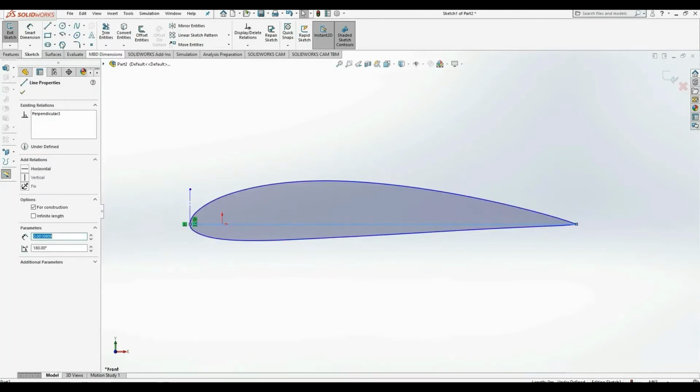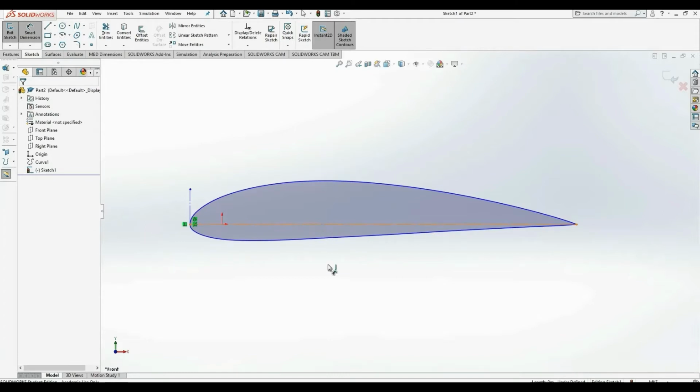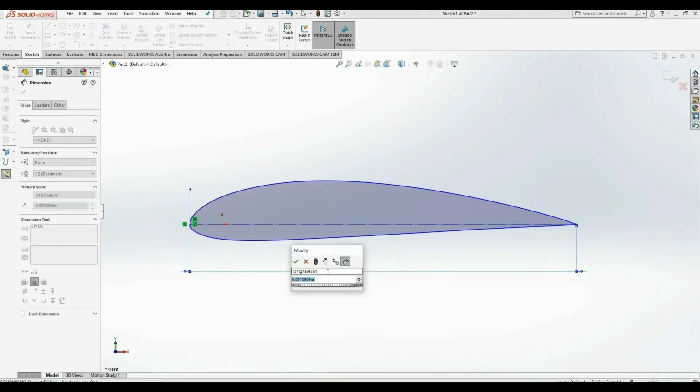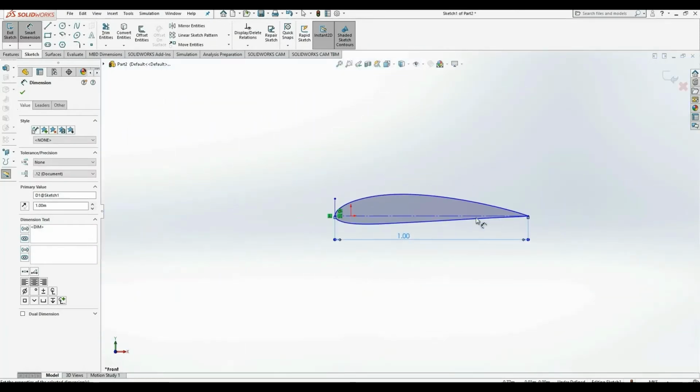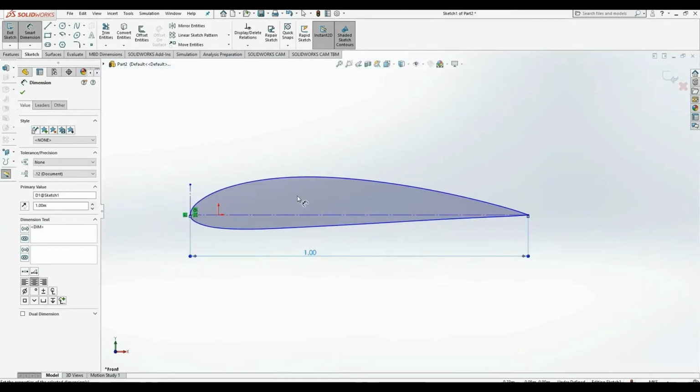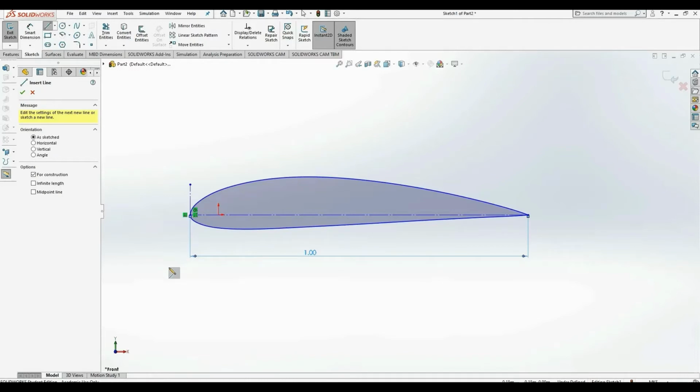So if we remove those dimensions, what it would allow us to do is change all of these different directional aspects, changing the angle of attack. So at this stage I'm going to now change my measurement to be in meters, so I have a 1 meter chord aerofoil. We can adjust that to whatever size we might want at a later point.